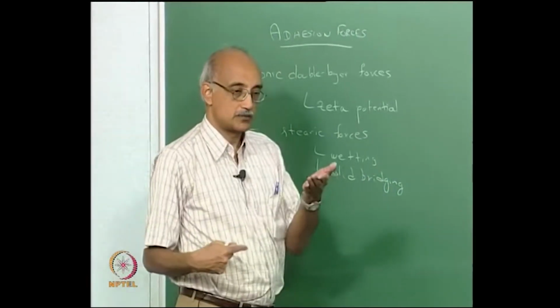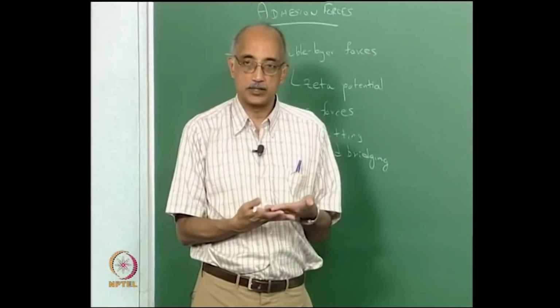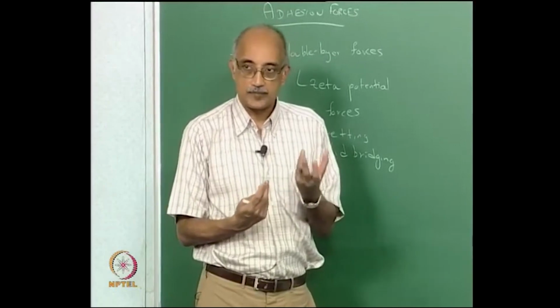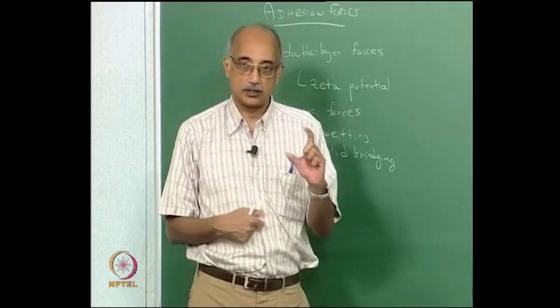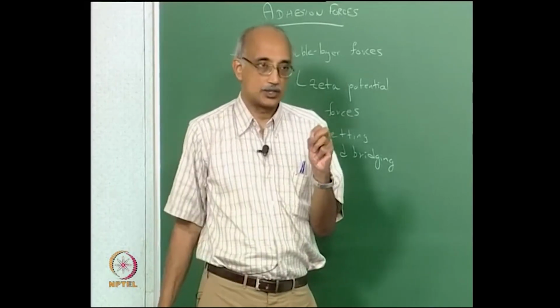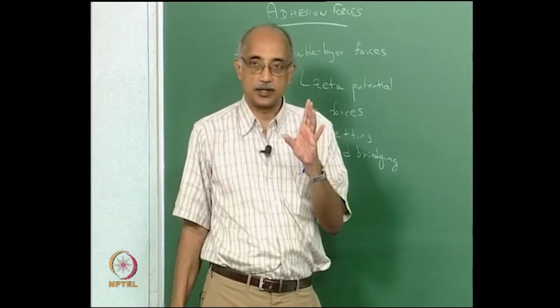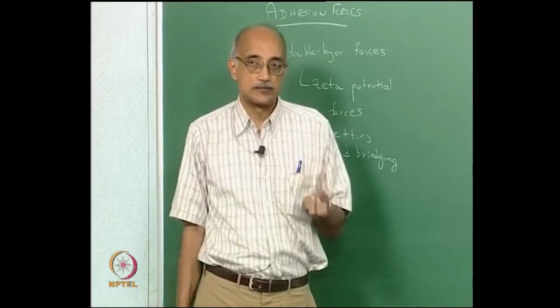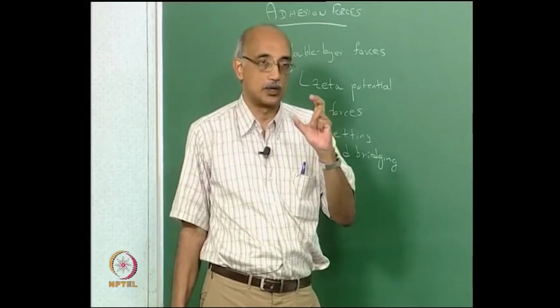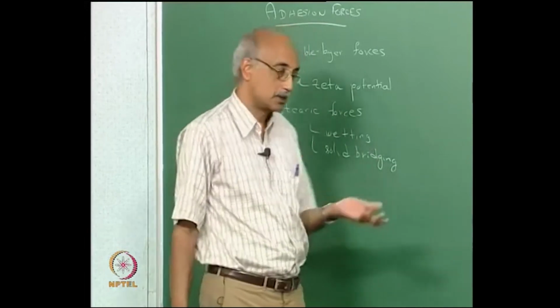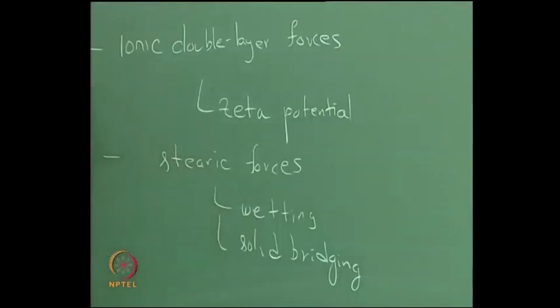When a liquid first wets the interface between a particle and the surface and provides an additional adhesion force, that is called a wetting action. Now, if you take that same interface and you dry it, then the adhesion force actually increases by several orders of magnitude, because the liquid that is trapped between the particle and the surface now solidifies and actually forms a solid bond between the two. So, that is called solid bridging.